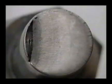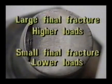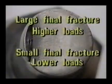This fracture exhibits beach marks, ratchet marks, and a final fracture that is ductile. The texture is smooth and silver gray in color. This is a fatigue fracture with more than one initiation site. The size of the final fracture is an indication of the severity of the applied load. Large final fractures generally indicate large loads, while smaller final fractures indicate lower loads.